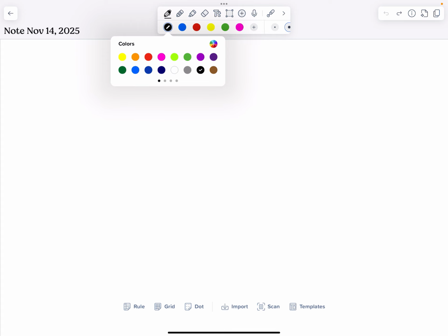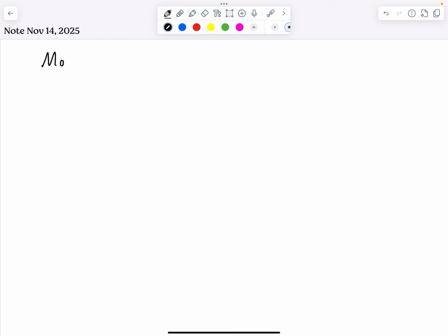In this chapter so far, we've looked at how we can use dimensional analysis and the Buckingham pi theorem to develop these relationships between different pi groups. And now we're going to return to this idea of modeling and similitude to show how we can use those concepts. The example we talked about earlier in class was this idea of developing a scaled down version of an airplane wing. And let's say you take force measurements on that wing. Well, how do you know that those relate to the large scale original version as well? So that's what we're going to talk about today with this idea of modeling and similitude.